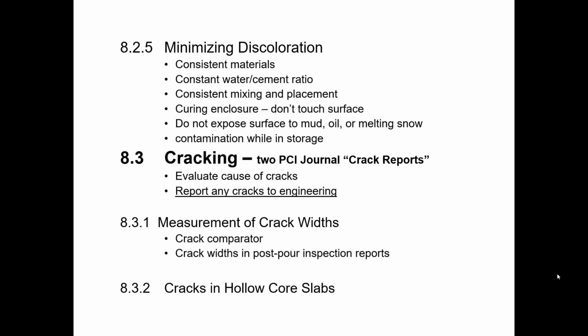See, will it come off if you scrub on it a little bit with a brush? Something that's not going to damage the panel, but that is stiff enough that it might remove that staining on the surface. You can also try an abrasive blast with something like baking soda that's not so abrasive that it will damage the surface of the concrete, but it may take off the efflorescence.